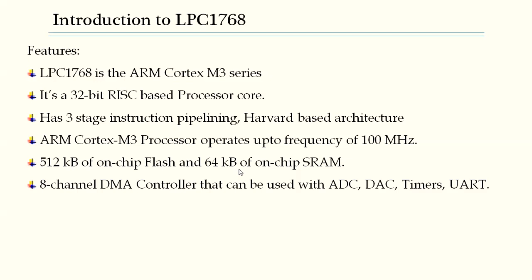Similarly, converting digital to analog is the functionality of the DAC block, wherein the processor is not really required. But nevertheless, the ADC requires some data to be accessed from the memory, sent to the memory, and so on. The controller transfers the control to the DMA controller during these operations. That's the job of the DMA controller, mainly whenever the operations are related to the memory wherein the processor is not really required.